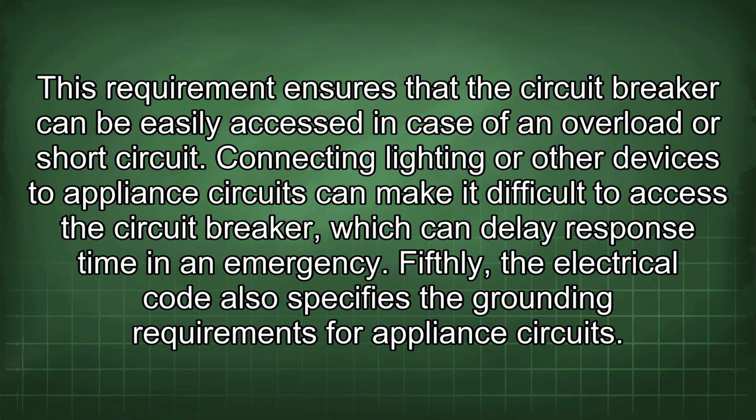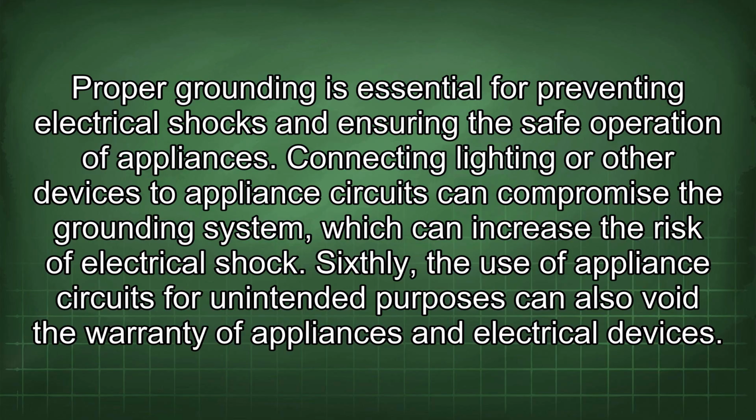Fifthly, the electrical code also specifies the grounding requirements for appliance circuits. Proper grounding is essential for preventing electrical shocks and ensuring the safe operation of appliances. Connecting lighting or other devices to appliance circuits can compromise the grounding system, which can increase the risk of electrical shock.